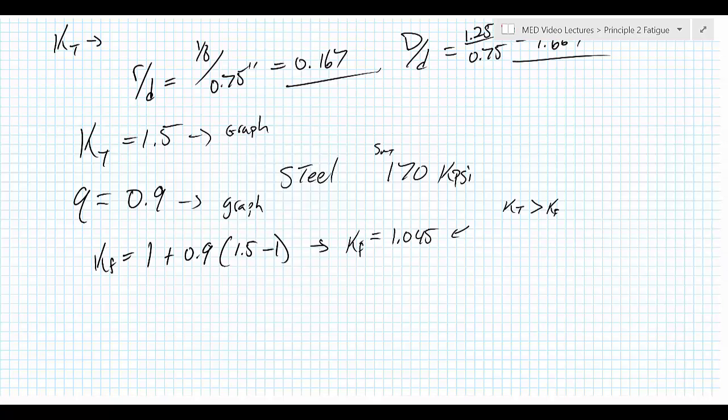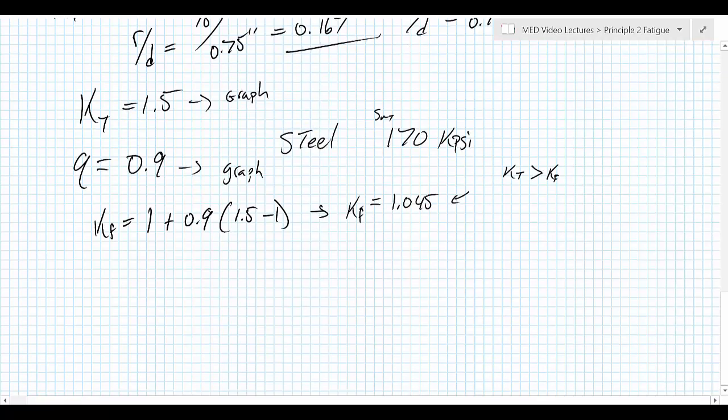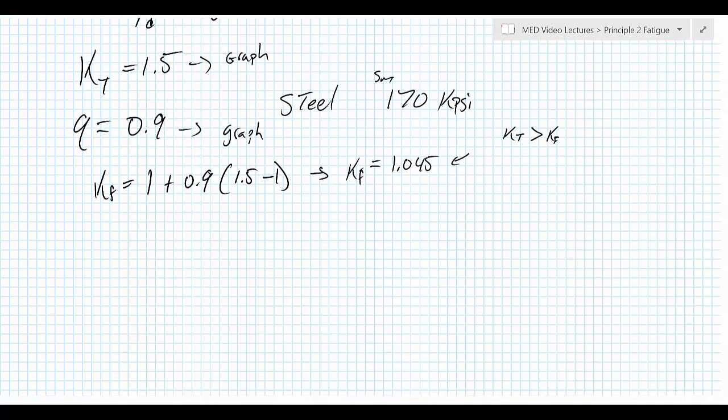So if you have absolutely no idea how to figure out your notch sensitivity for a material, say you don't have a table or chart for it, if you use just the hypothetical stress concentration factor, know that it's okay. You're just going to have a very conservative value. It's going to be a little higher than it needs to be, but at least you're making mistakes in a more conservative direction. All right, so now let's put this all together.